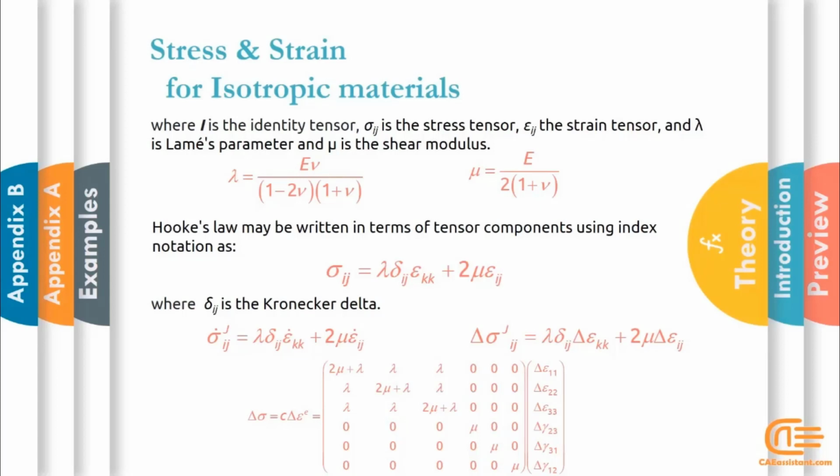Calculate the amount of stress at each step and calculate for the next increment. 2. To calculate the stress, the Jacobian matrix must be written in the code. 3. Before that, we need to get the values of the components of this matrix from the theory of plasticity and elasticity and so on.